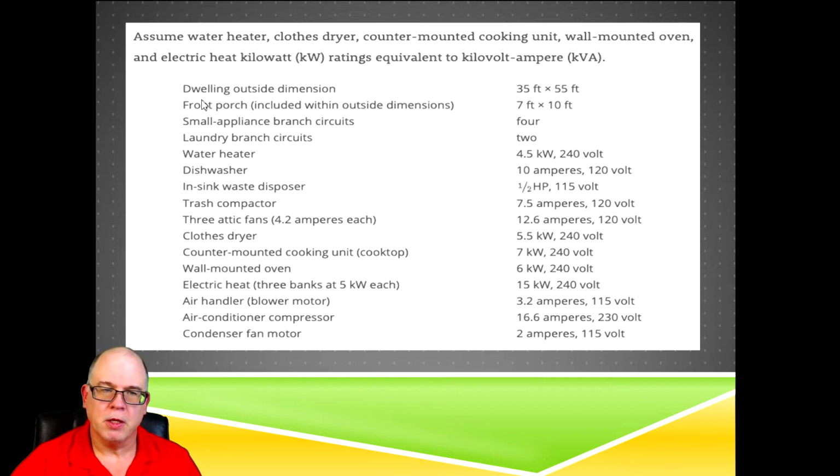Okay. We have small appliance branch circuits. The code requires a minimum of 2, and that is in the requirements in 210.11(C)(1). And in this case, we have 4 that we're dealing with. So we've got 4 of them that we've got to take into account for this optional method. And remember, in the standard one, we had the same concept. We had to do 4.